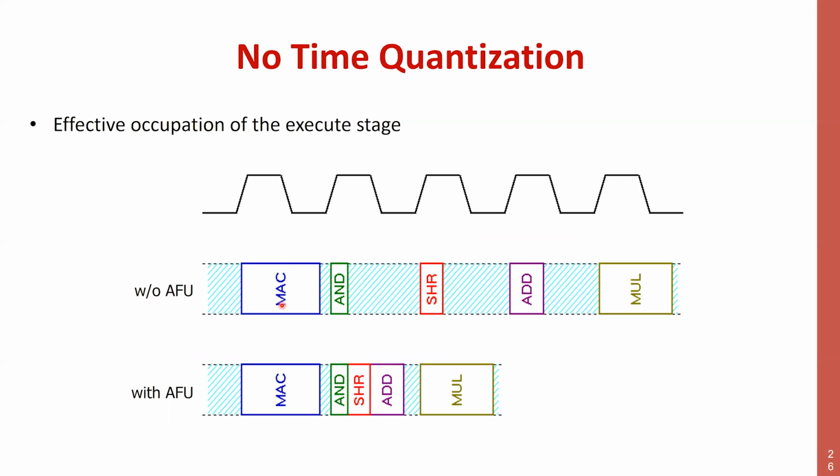But whatever choice I make, I always have operations that are of very different complexity, right? And the complexity in terms of time taken to really execute the operation is probably even underplayed here, right? And is extremely fast. I go through 2 transistors. The critical path is 2 transistors. Add is hundreds or thousands of transistors. So it's much longer, and multiplier is tens or hundreds of thousands of transistors. So the length of the individual instructions is very different.